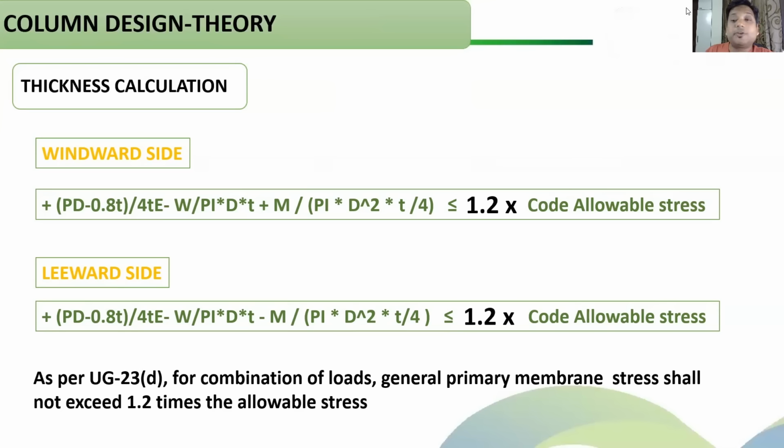So this is the basic philosophy behind the thickness calculations of a column shell. It is a little different from your pressure vessel design. There are some additional loads which become really critical here. So thickness may be governed by longitudinal stress. Now, apart from this, do you think any other kind of load may govern the thickness calculation? I want you to think of any other mode of failure which your column may see. Think about it, and then move to the next section.